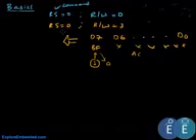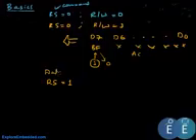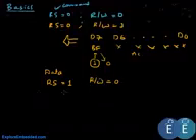Now the next command would be, the register select would be 1 in this case, and this is pretty important. So this makes it a data register, and what we usually do with this is we write data to the LCD. So the read write again would be 0. So we write data to the LCD. Now what we could possibly write is the ASCII characters.